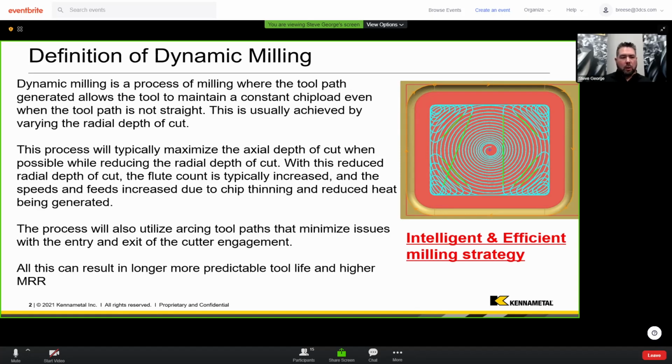Probably a lot of you are familiar with the really old work done by Taylor in terms of tool life diagrams and things like that. We're still interested in that stuff today. But when we go into that, what are we usually doing? Usually we're testing different speed conditions, right? And we see that tool life follows a logarithmic pattern based on cutting speed.